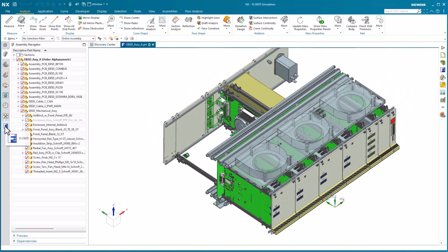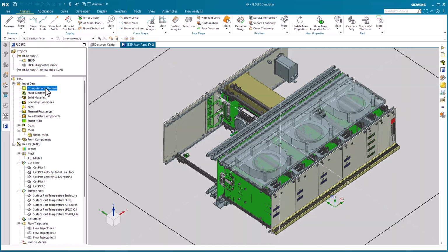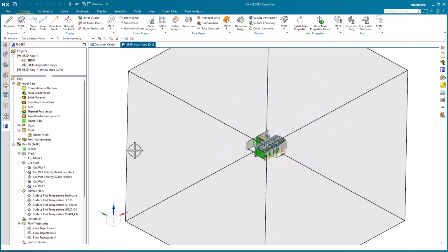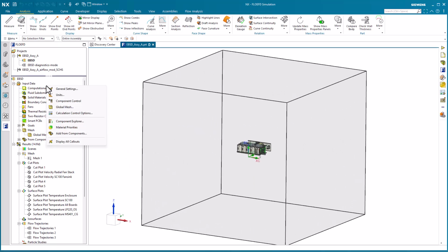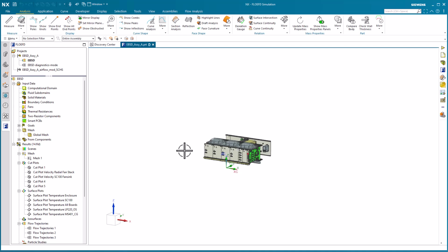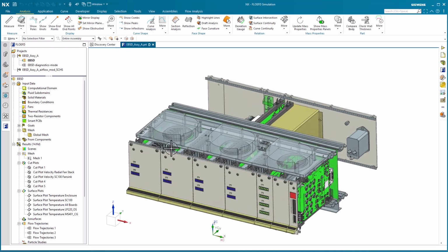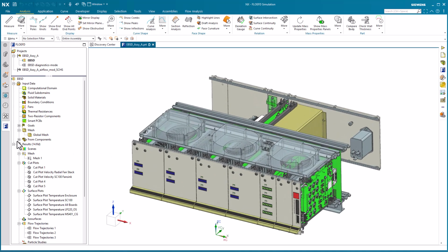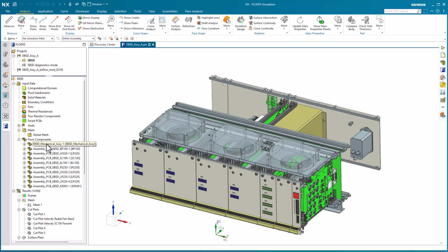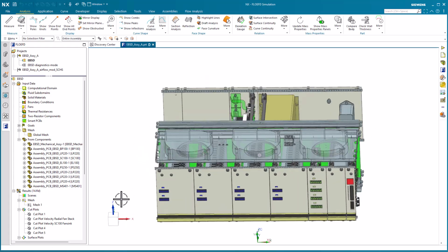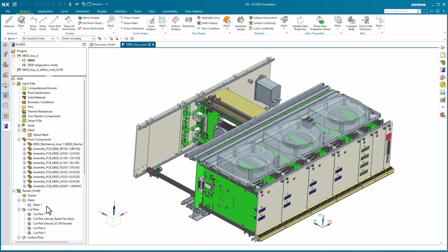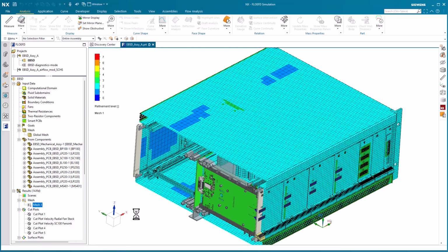The FlowEFD thermal analysis process is ostensibly the same. The computational domain size is defined and can be seen. The sub-assembly FlowEFD projects are all inherited by the top-level assembly, so no individual boundary conditions need be applied. This makes the project very modular if we need to use any of these PCBs in a future product. The mesh is significantly larger and the runtime proportionally so.